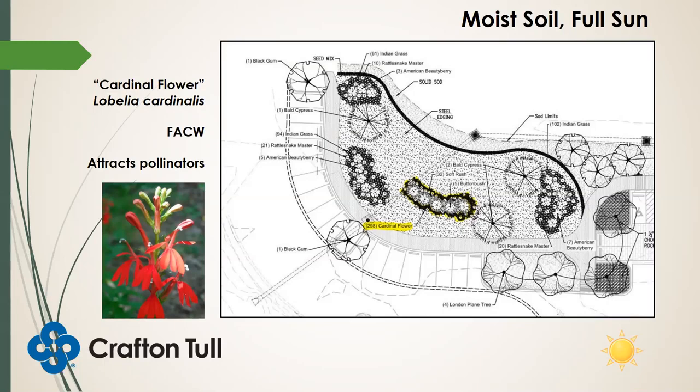Let's see, it appears it's all predicated on being in a climate zone where the rains will be frequent, so the lower portions of the rain garden will always be wet. Have you dealt with situations where the whole bed will dry out for long periods? I personally don't have direct experience with that. I mean, we get pretty wet here in Arkansas. I would recommend, though, if you're going to have a dry bed, make sure you're choosing species that are either facultative upland or upland species.